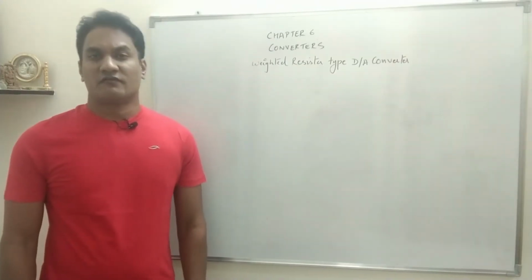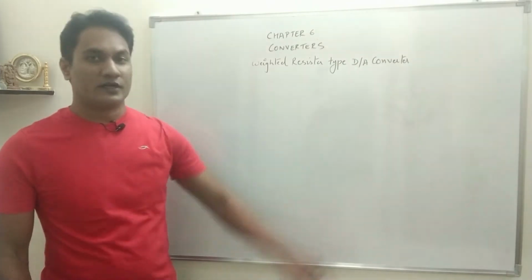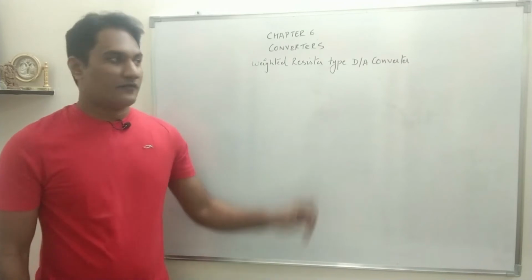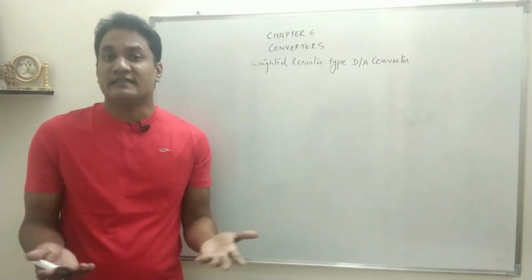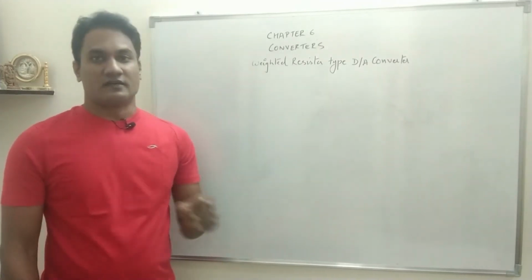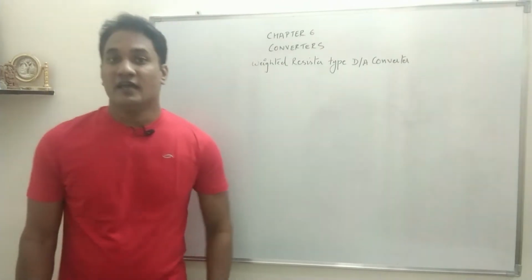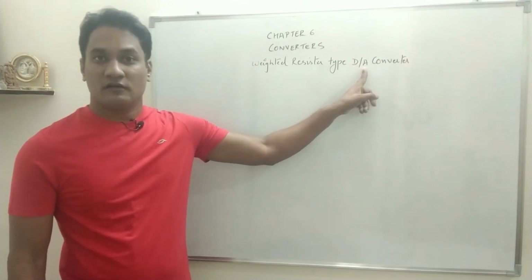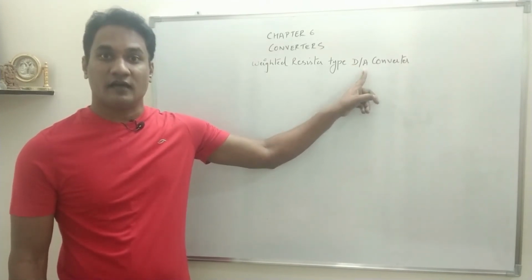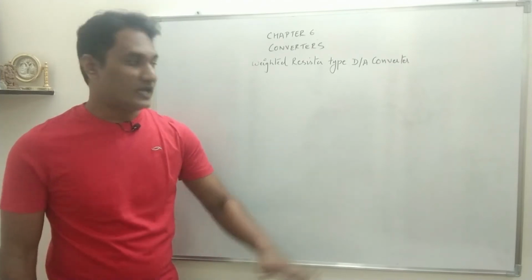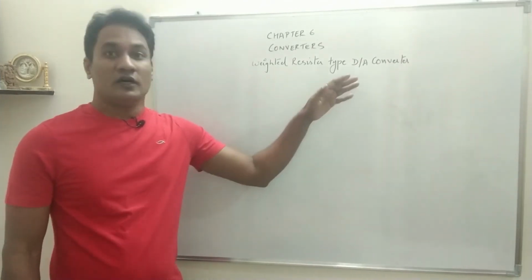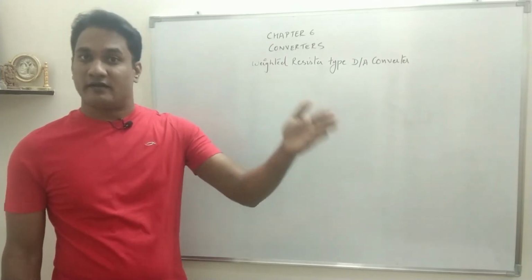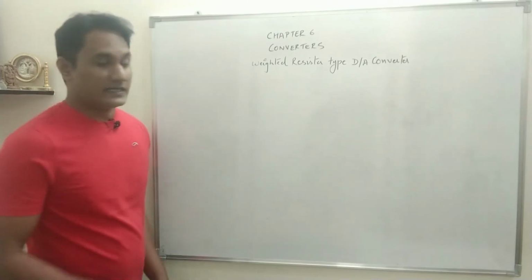The first converter we will try to understand is a D2A converter called the weighted resistor type D2A converter. Of course, resistor here means resistance. Let us try to understand what exactly we mean by weighted resistor. Now we are converting a digital into analog. That means the input will be binary data and the output will be a voltage level. So for this circuit we have to derive an output voltage equation, which converts a binary value into analog voltage.